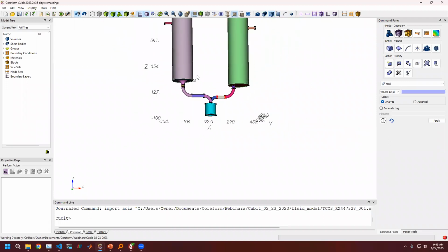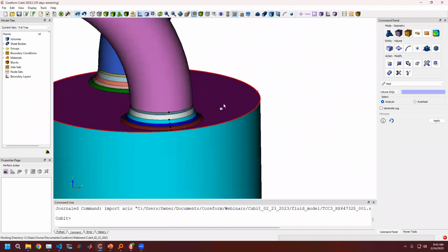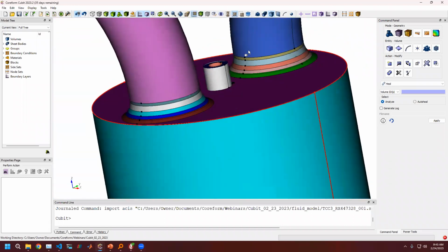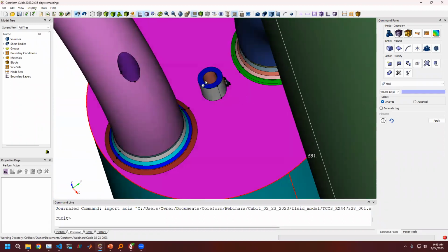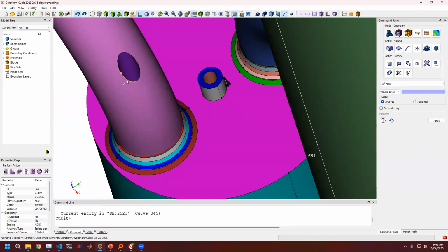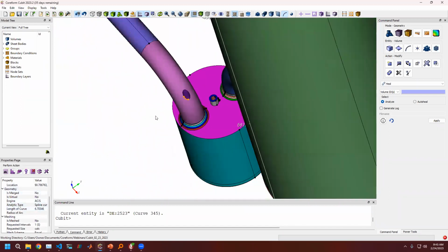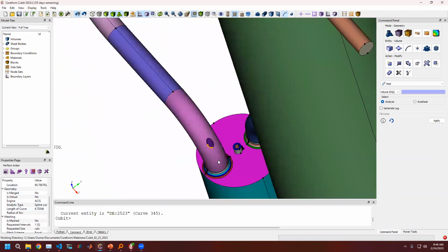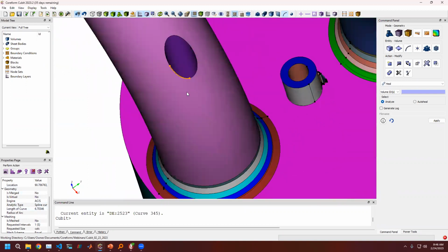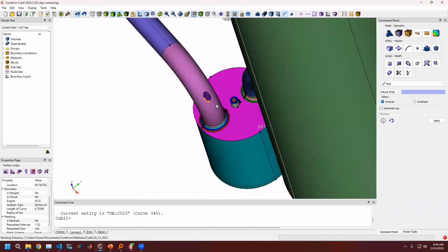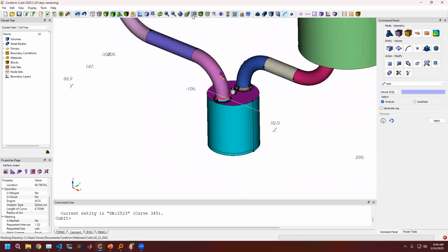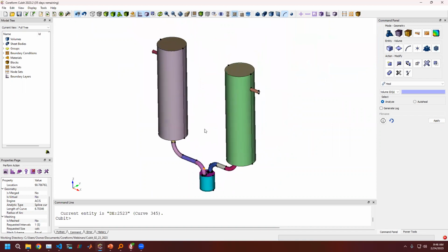The first thing is, I might look through my model and try to decide what kinds of length I want to keep in my model. I know I'm going to get rid of this entity here, but I can see maybe trying to keep something like this. Length of the curve is about 6. That's probably for now maybe the smallest feature that I care about. So I don't really need to scale this much at all. I could scale it down by a factor of 10, but I'm going to be pretty well scaled here. So that's check mark number 1.